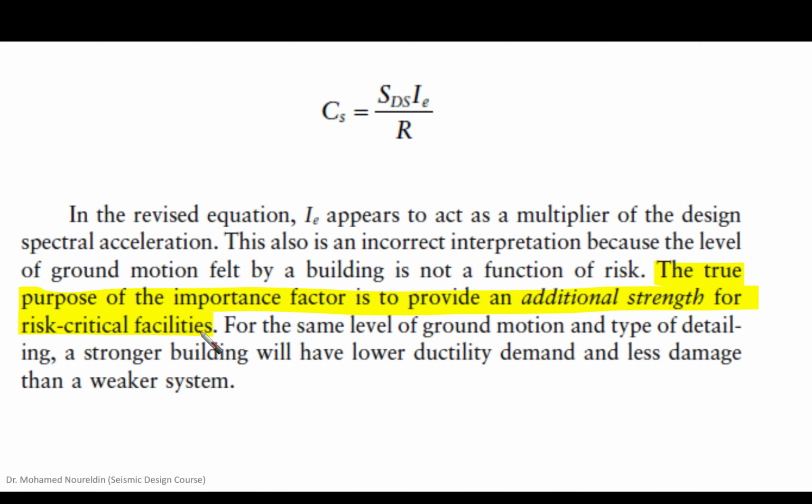So the true purpose of the importance factor is to provide additional strength for risk-critical facilities. That's it. Whenever I ask you what the main purpose of the importance factor is, it has nothing to do with SDS, it has nothing to do with R, but it is only for providing additional strength for risk-critical facilities.